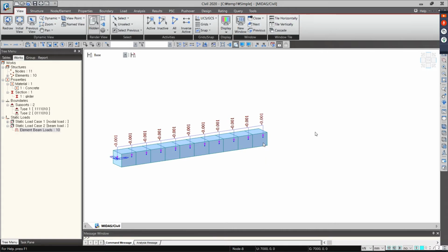If I only want to show kilonewton, that means the icon besides the kilonewton millimeter will disappear. The unit of beam load should be kilonewton per meter, so it should include the length of load value.